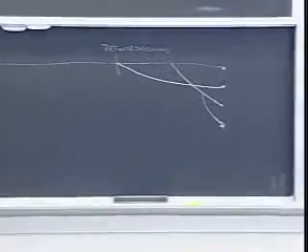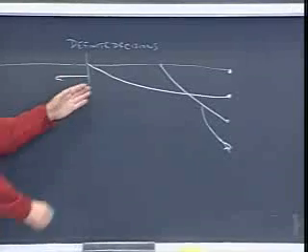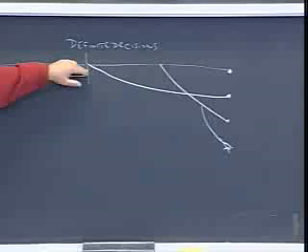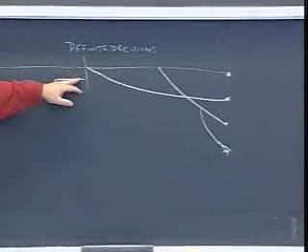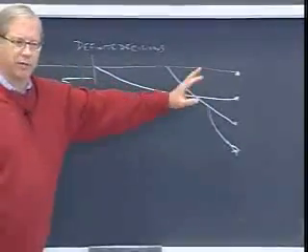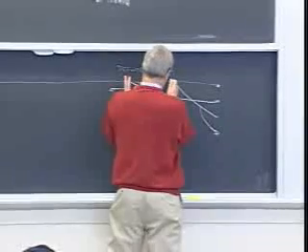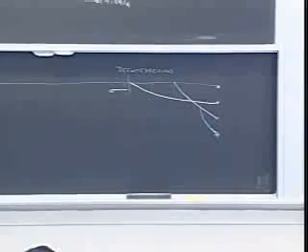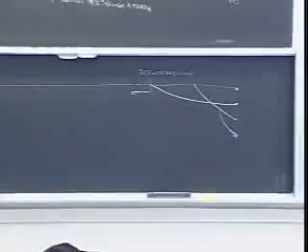All right, so one way to operate the Viterbi algorithm would be, at this point, to say, okay, I'm going to put out everything before this time. No matter how long I run the decoder, the first part of it is always going to be this part. So these are definitely decided up to this time. And then I still don't know about here. I'm going to have to go a little bit further. You proceed further, and after a while you find more that's definitely done. In practice, that would lead to a sporadic output rate. That isn't really what you want.